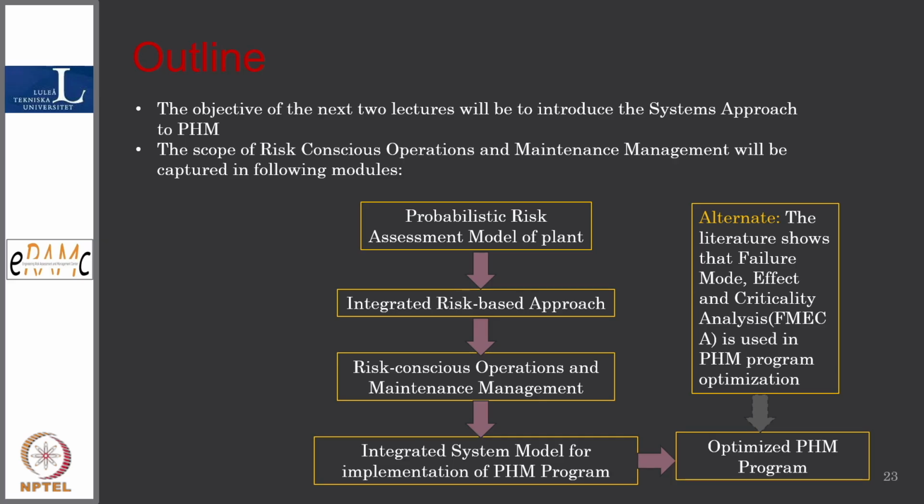But probabilistic risk assessment is something where, when you have the design of the plant, a PRA model is created wherein safety systems are developed, and process system failures account for the initiating event. Let us say, for example, loss of offsite power is an initiating event in the plant. And then the safety systems, such as emergency captive power, diesel generator or battery banks, respond. They are characterized in terms of probability, the probability of their activation given a demand. So, we have an integrated risk based approach.